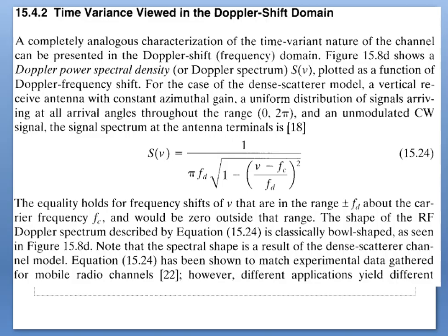Thus, when the time interval between the fades is approximately lambda by 2, the resultant expression for T naught is quite choice. By considering some mean parameters, like velocity equal to 120 km per hour and carrier frequency approximately equal to 900 MHz, it is straightforward to determine the channel coherence time, approximately equal to 5 milliseconds, and the Doppler spread, approximately